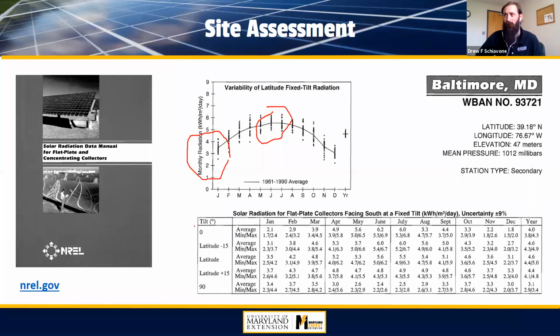You also see them given as a function of the tilt angle, and we'll talk about that. If you lay your panel flat on the ground, pointed up, of course, it's not going to be as efficient, and you'll see that reflected in the values in this table. So we'll talk about the tilt, but if you want specific information, you can use resources like I've shared here to get more of a local level of the solar levels.